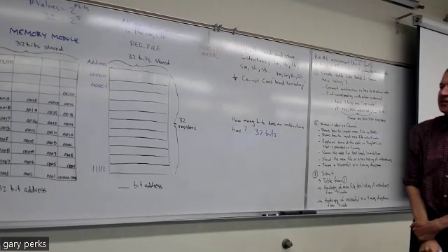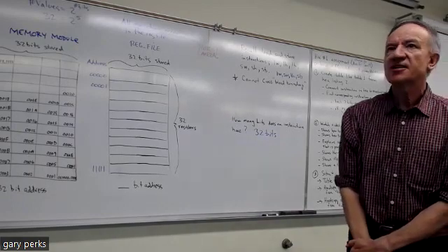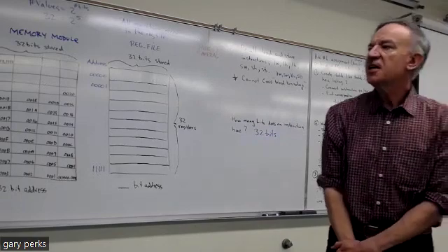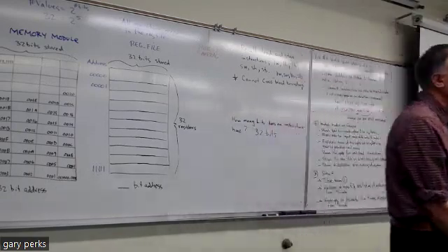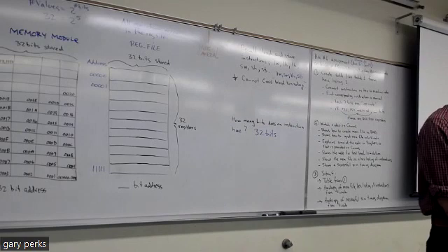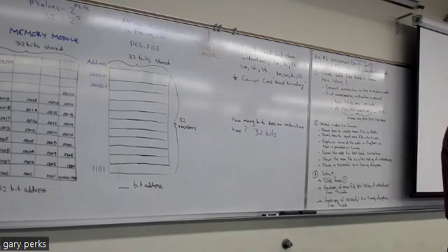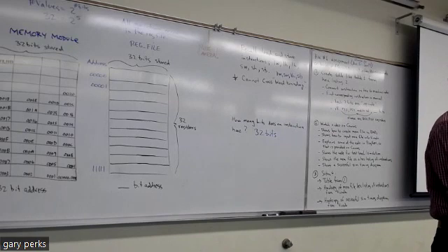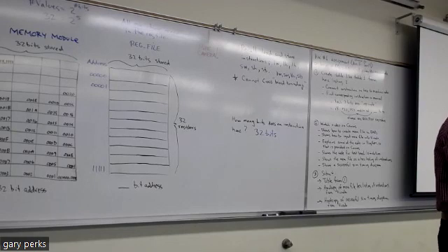All right, so the next thing to talk about, and I think we have enough time before taking a break, is how the Otter is actually programmed. Like I mentioned at the beginning, we can't program the Otter like an Arduino, where you just download the file right to the Otter. The way it's done is that we use RARS to generate a mem file, and that mem file has a hex listing of your program. All the instructions in your program are in hex.